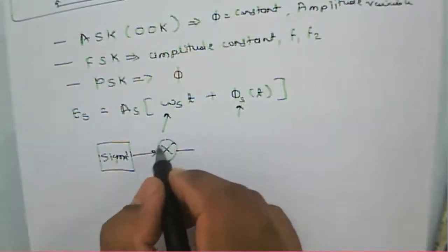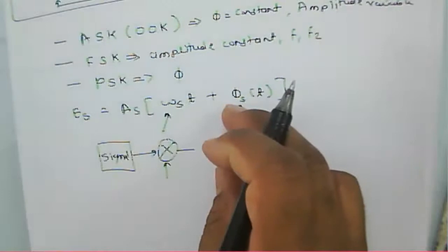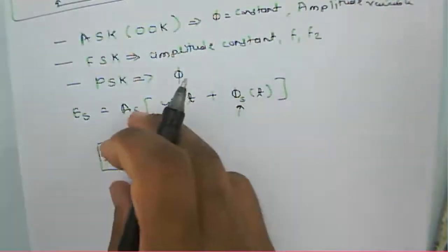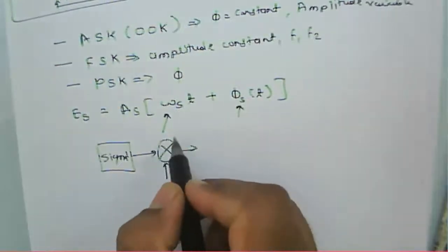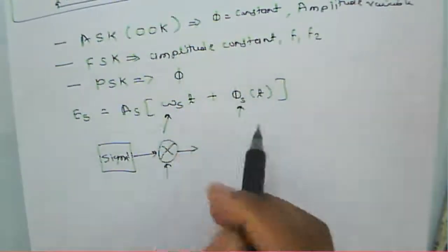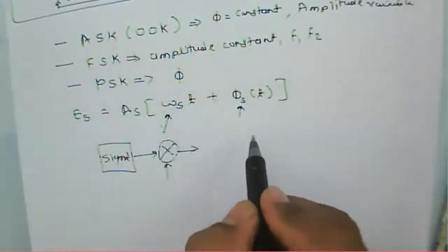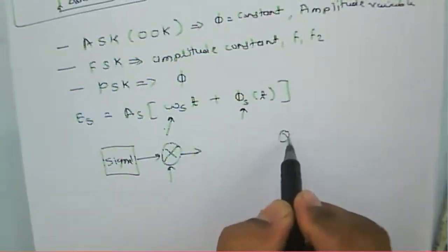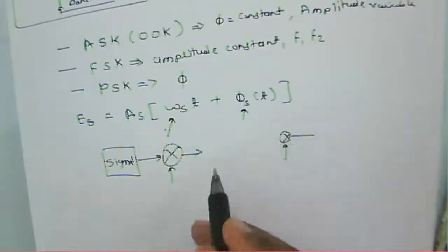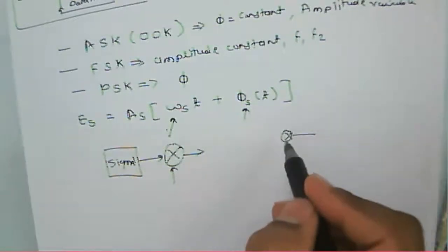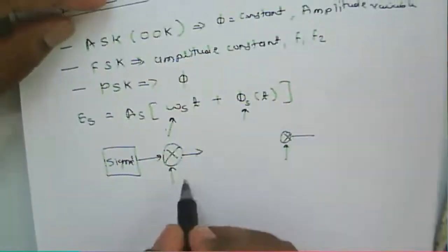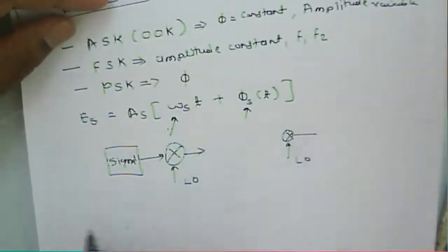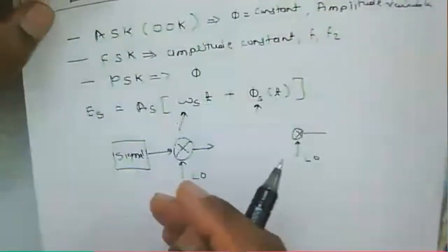So either we can use an up conversion or we can use a modulator and convert the signal to a higher level, and then we get the signal out here. Similarly, at the detector, we need to use a demodulator or again a mixer to convert whatever output we have. We use a local oscillator for the conversion or for the modulation.